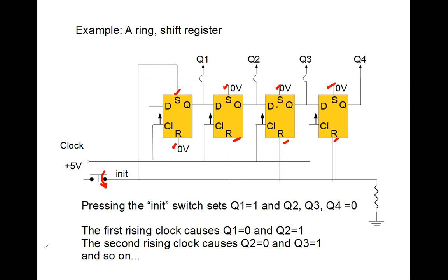So now what happens when the clock comes through? As the clock is pulsing in this line, and notice it's also pulsing here, here, and here, we transfer the value of the first stage to the second stage. So this 1 goes to this flip-flop, and now this flip-flop becomes a 1. This flip-flop was a 0, so that 0 is propagated to the third flip-flop.